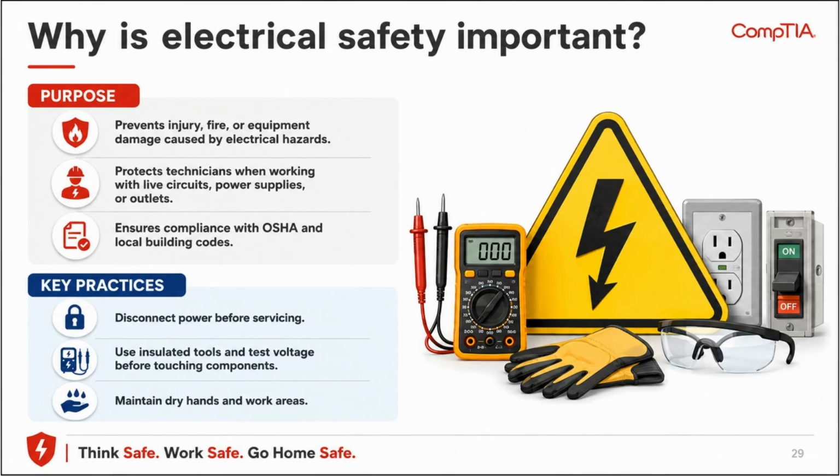Electrical safety prevents injury, fire, or equipment damage from electrical hazards, protecting technicians working with live circuits, power supplies, or outlets, and ensuring compliance with OSHA and local building codes. Key practices: disconnect power before servicing, use insulated tools and test voltage before touching components, and maintain dry hands in work areas.